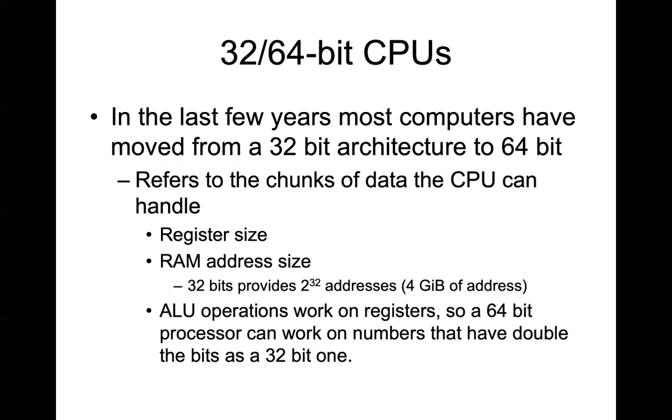The simple computer was what we call an 8-bit architecture. The reason we can know it's an 8-bit architecture is because registers contain 8 bits and instructions that are loaded are 8 bits. So we might also expect memory addresses to be 8 bits, but they're not. They're only 5 bits on the simple computer. But still, it would probably best be understood as an 8-bit architecture because that's the size of the registers.